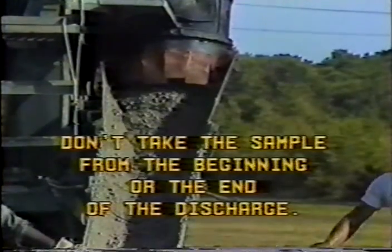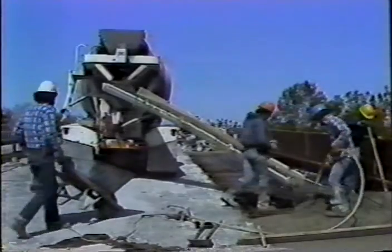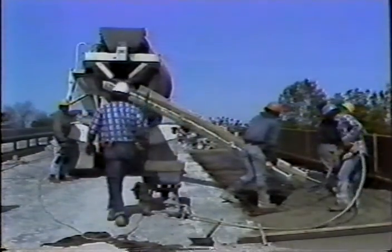Actually, the word sample isn't quite enough. What you're going for is a representative sample. You want to make sure the concrete that you're testing is typical of the entire truckload. The basic rule in sampling concrete is this: don't take the sample from the beginning or the end of the discharge. At least 3 separate samples have to be taken. I'd suggest taking them at about the 1/3, 1/2, and 2/3 points.